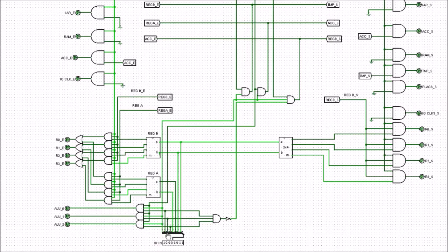into the 8 bits, and the most significant bit is a value of 1, which tells us it's an ALU instruction. The next 3 bits tell us that it's going to be an add, and the 10 tells us that we're referring to reg A, and we're referring to register number 2 from reg A, and register number 3 from reg B for these 2.